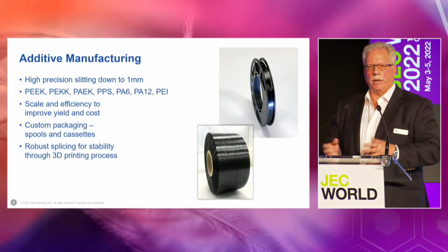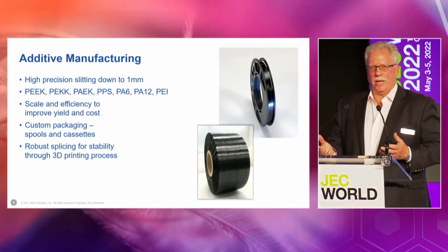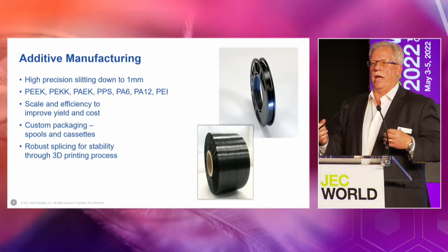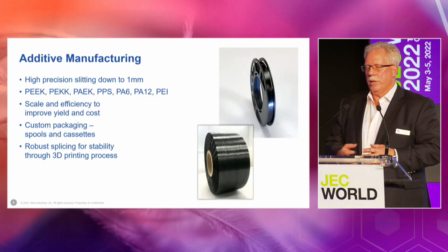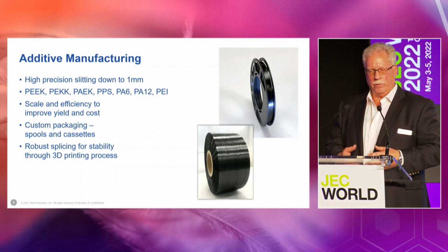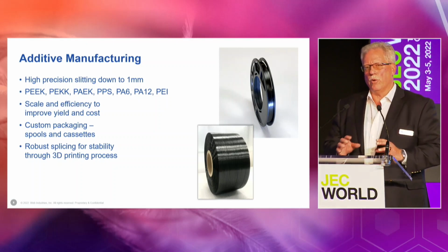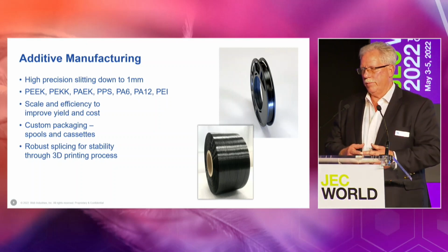We're also involved with additive manufacturing, which is an up-and-coming technology for aerospace, because they want to use the same materials as the AFP and ATL, right? Because these are already approved materials. There are specs for them. There's probably NCAMP certification for some of them, but it allows the additive manufacturing developers to use homogeneous materials that already have approval. So it potentially reduces the requirements for part approval, and helps on the design because allowables are there to design using these materials. And again, it's the same that we use for AFP and ATL.